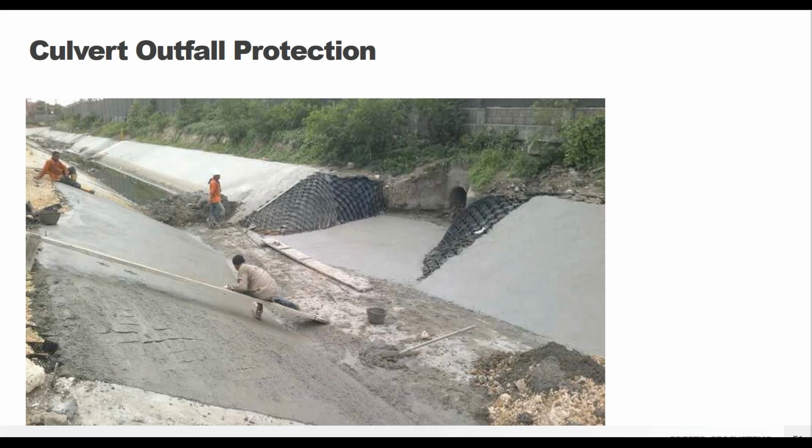Using the GEOWEB system can help mitigate some of these concerns, especially when concrete infill is used, since turbulent flow and high velocities aren't going to be an issue when concrete is used. The option to mix infill types, going from concrete to stone or concrete to soil, is going to be really helpful when you have to protect against these areas. So use concrete around the outfall area and then transition to something else for that more aesthetic appeal when you know that you've reduced your flow enough.